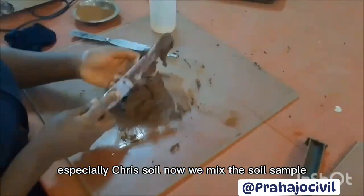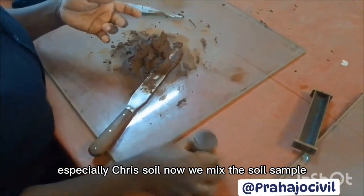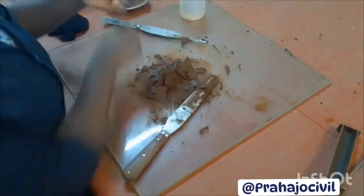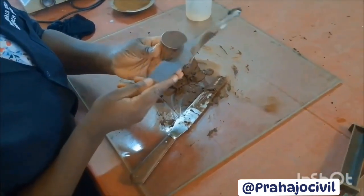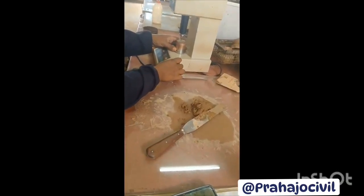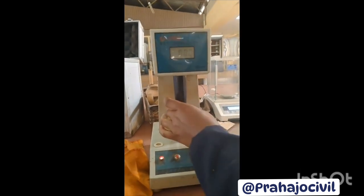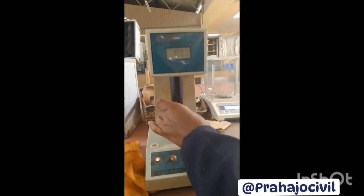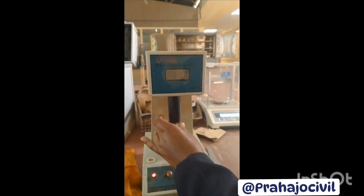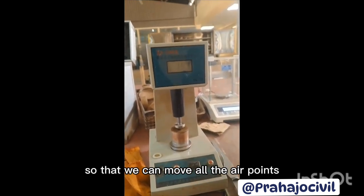Now, we mix the soil sample well, uniformly, until it attains a homogeneous paste. Then we use our cone penetrometer method. That's a cup. We have tapped it on a firm ground or a rubber so that we can remove all the air voids.